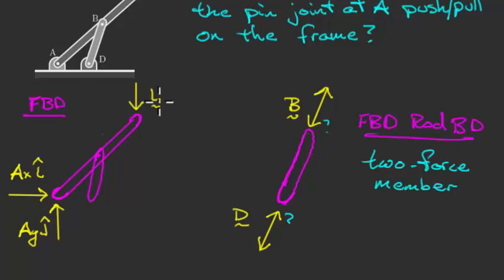So what I'm going to do here on my original free body diagram, of the entire frame, is put this force acting on point D, or from pin D. I'm going to draw it like so. Again, it is acting through point B right there, something like this. So I'm going to label it D. And once again, maybe this is important on your free body diagram, we don't know the precise direction. We know it's acting through point B, but it could be downward or it could be upward.